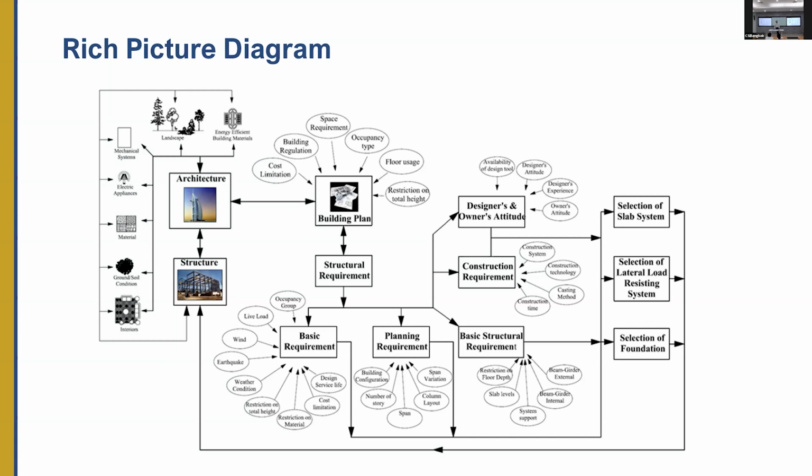The original structural designer, and the floor post-tensioning system designer. And so you say, okay, I'm designing this one, you're designing that. It's not a good situation. So the main designer must know how to design post-tensioning also, and then leave some detailing to the contractor, or at least check the design back. So that's another area that engineers need to learn.